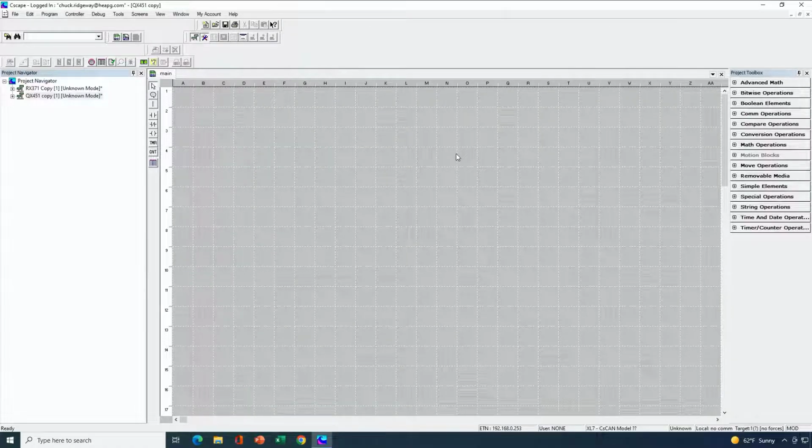There's technically three scenarios. One scenario is the resolution of the original unit is identical to the resolution of the new unit. That's a perfect scenario because you don't have to do any stretching at all or any scaling. Of course, if you're going from low resolution to high resolution, you can use the Fill All Screens function and then clean up after that. If you're going the other direction, like I just did, you're going to have to manually manipulate your graphics smaller to fit within the new confines of the new unit, and then change your hardware configuration.